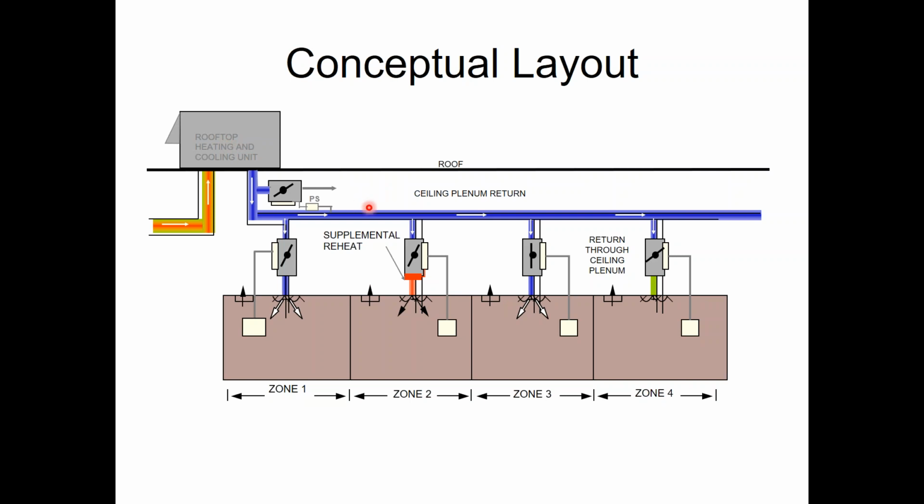So I didn't get to pick any equipment. I didn't get to decide how big it was. None of that stuff. I didn't size the ductwork. It just is what it is. So what I would do in those cases is I would be opening up my zone dampers when the air balancer is at the site with me. And granted, this is assuming someone hired an air balancer, which only happened like 60% of the time. And I have the air balancer hooding these guys to see if he's getting the airflow that he needs or not. And then I can back my system down on the static pressure set point to accommodate what he's seeing for the airflows on these guys.